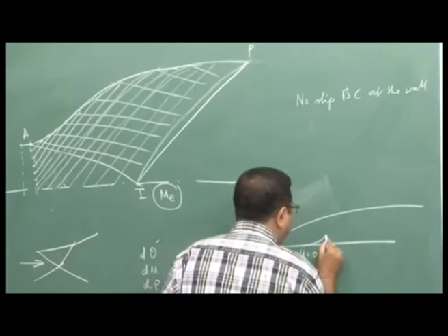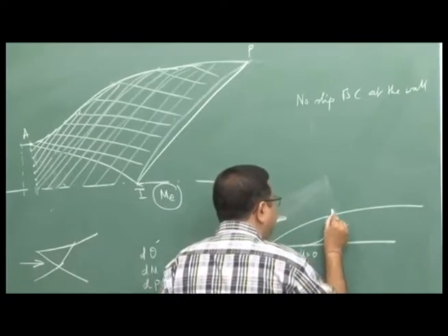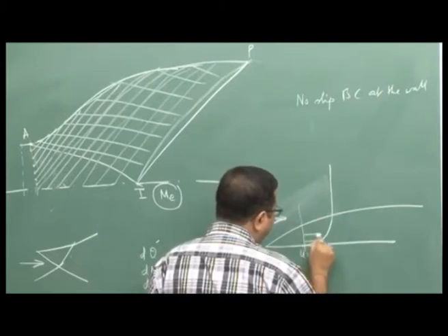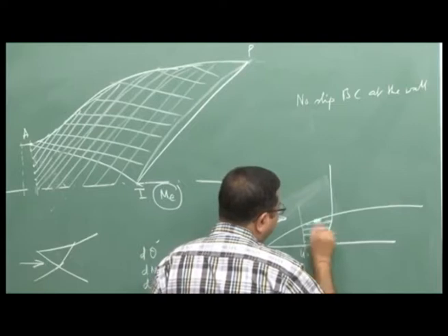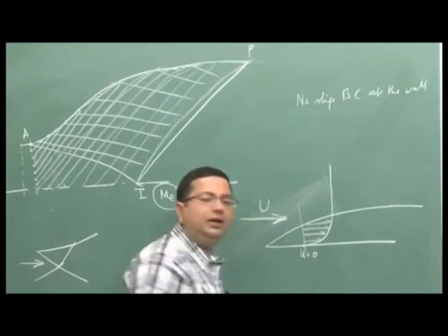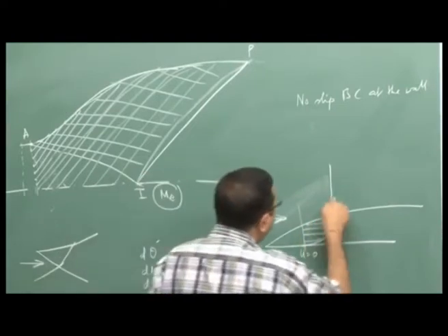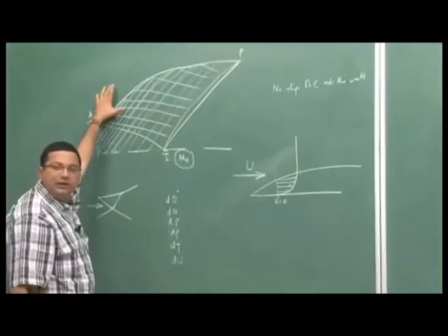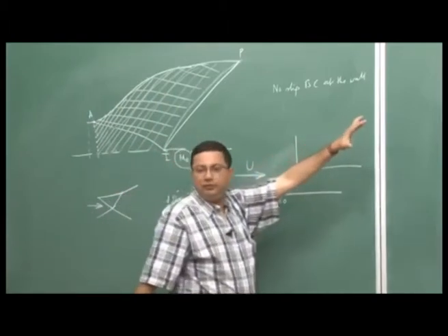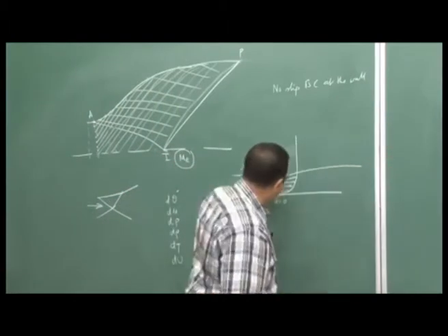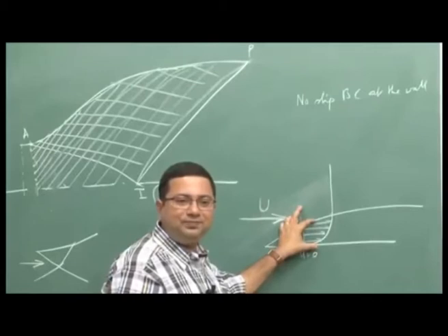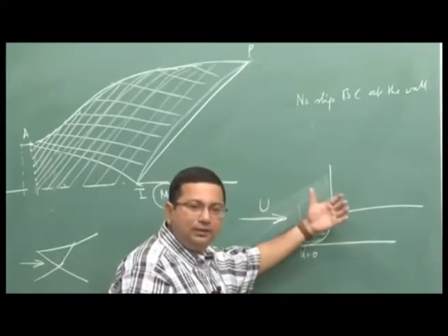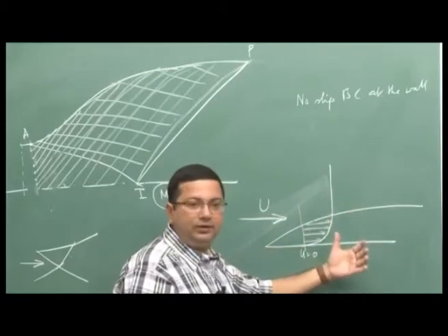Across this boundary layer there is a gradual increase in the flow velocity till it reaches the free stream velocity here. So, if I draw the velocity profile, it should look like this. At the edge of the boundary layer only it reaches the free stream velocity. However, for this method we have considered everything as free stream flow, we have not considered this boundary layer, and that can to a certain extent bring in a lot of errors.